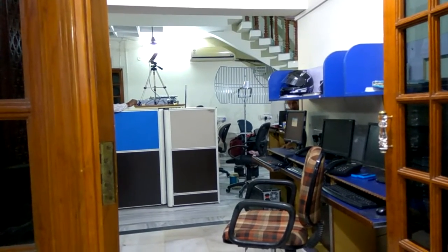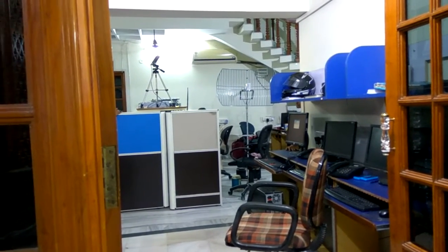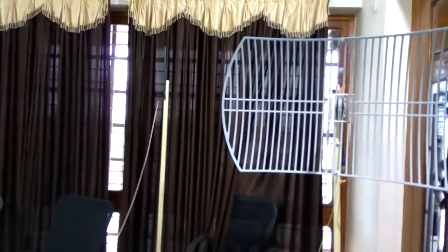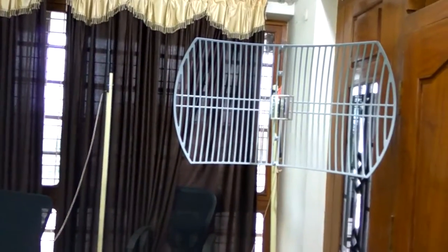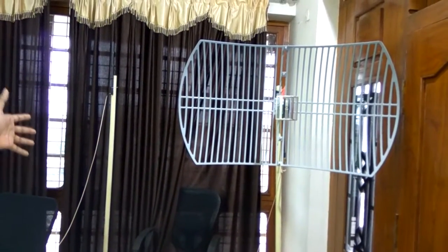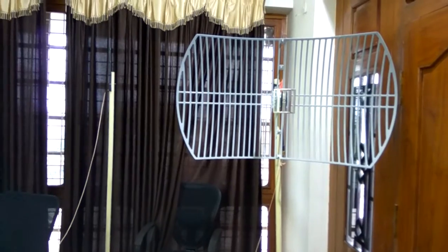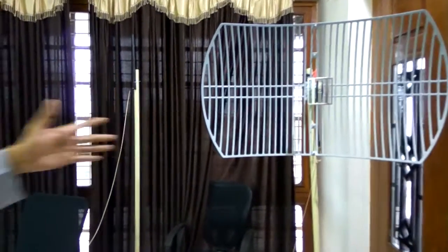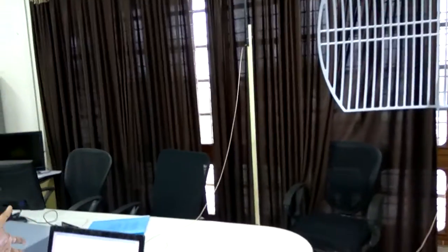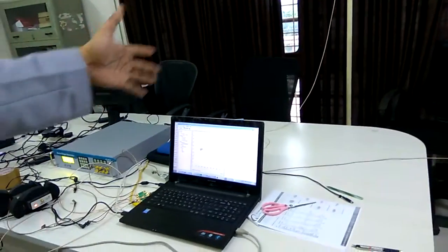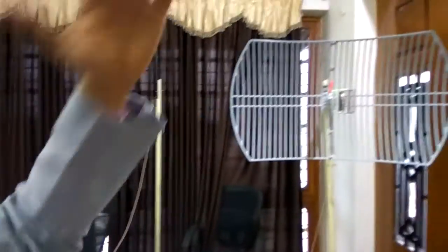When it radiates the radar signal, the radar target simulator is the facility that receives it. The simplest form of this, you can call it a radar beacon facility. It receives the radar signal, then based upon the range settings, Doppler settings and whatever other settings you made, it generates the echo and radiates it back.